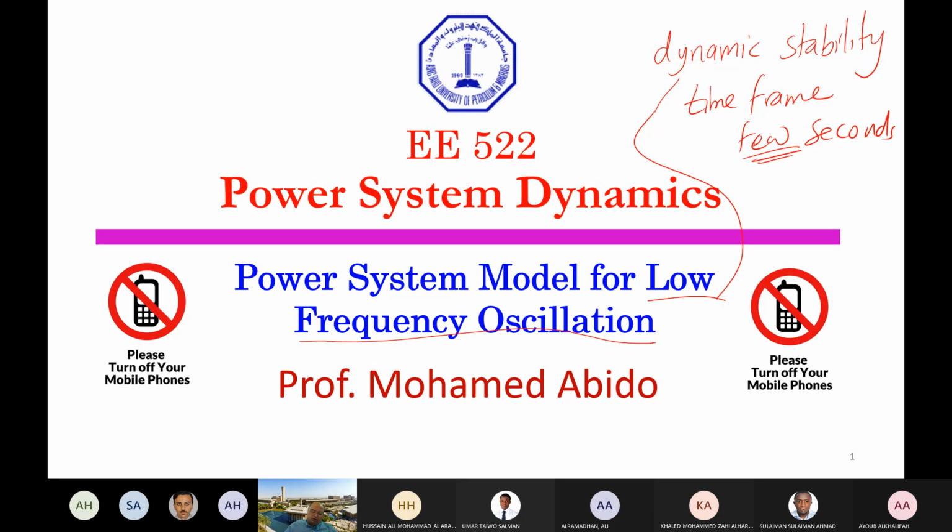Transient stability, of course, is a few milliseconds or a few cycles after the fault. Dynamic stability, or what we call the low frequency oscillation problem, is 5 to 10 seconds after the disturbance. In 5 to 10 seconds, you allow the exciter to improve the damping of the system.